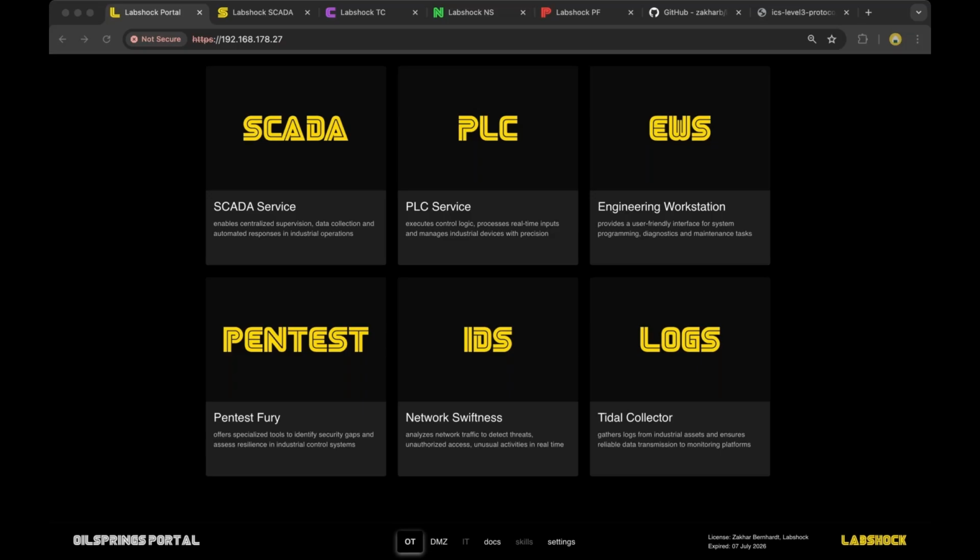What layered security approaches are recommended to secure Modbus? Segment your network and, let's say, turn off or make your switch ports unavailable for any unwanted connections. How do we prioritize patching or controls for patching? You know, it's hard to patch, and I think it's not a topic for today. Patching the PLC will not help you with open Modbus.